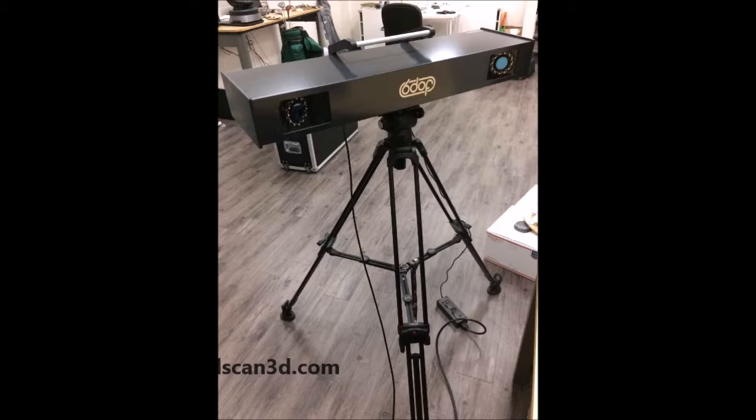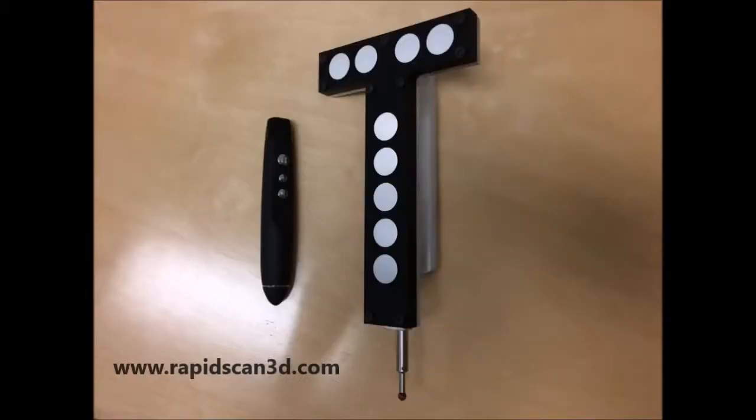It works by tracking the different sensors on the back of a stylus while utilizing the buttons on the clicker to register what point you want to register in your project. So this is the stylus that we're going to be utilizing in our project. It has sensors on the back of it so that the CMM machine can track the stylus position, while the clicker has 3 buttons on it. It has a button on the top, which is a laser pointer, a button in the middle, which is the accept button, and a button on the bottom, which is the cancel button. And we utilize those 2 buttons to select points and to stop collecting data when desired.